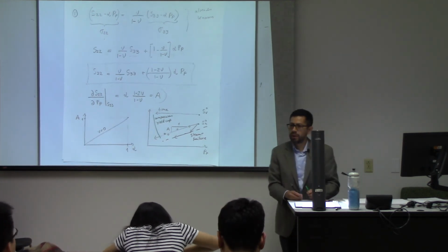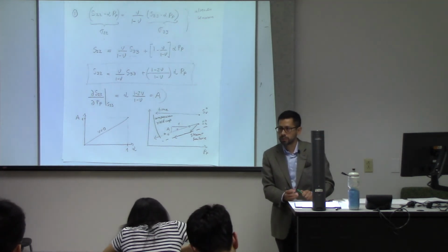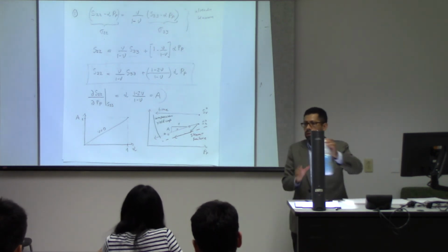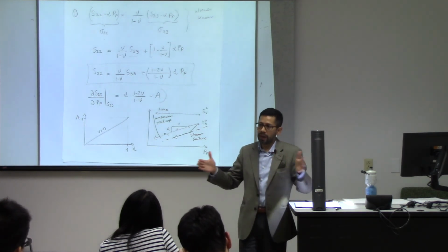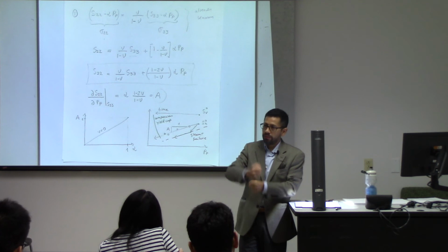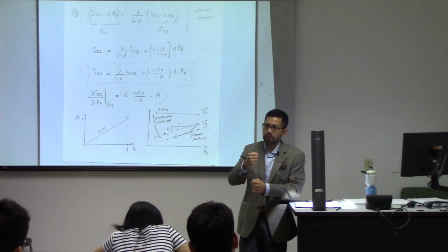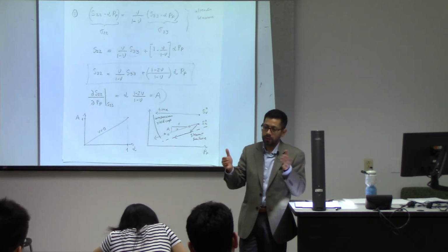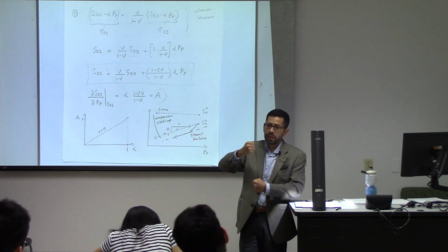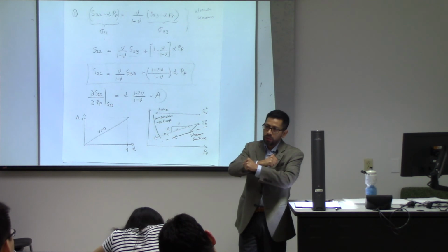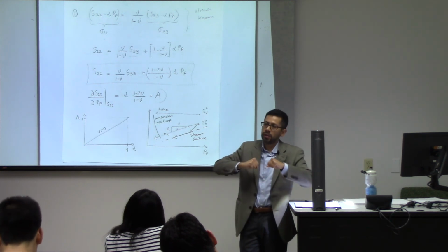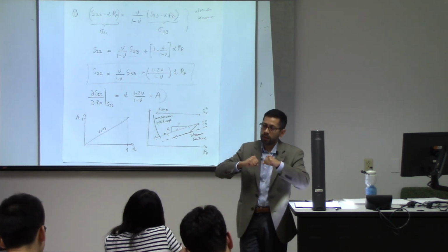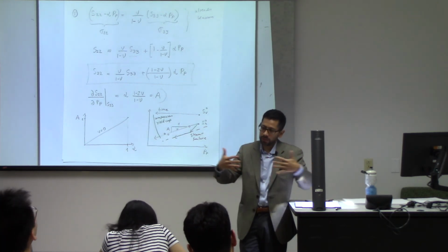So this is for Poisson ratio equal to 0. And what does that mean? What does a Poisson ratio equal to 0 mean? That the rock is not going to expand as you put more vertical stress into it. And notice that may not be good, because if the rock is not expanding as you put more stress, that means the rock has to take all the stress. It's not going to balance some stress by enlarging to the sides. If you let the rock enlarge to the sides, it's going to be able to resist more, because it's going to try to enlarge, but it's going to get some support from the sides.